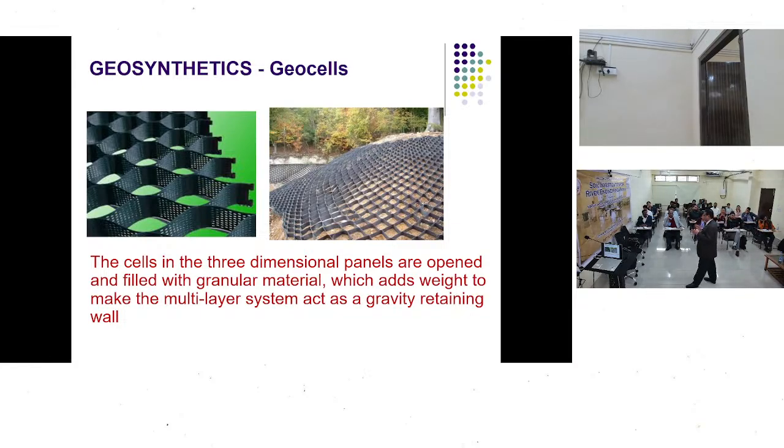Similarly, the granular material, if it is unconfined, can take a certain load only. That will be defined by its friction, the angle of friction, or in case it also has cohesion, you have the shear strength. That will define the maximum load it can take, which you also say in the form of bearing capacity. The bearing capacity of a material. That is how we define it.